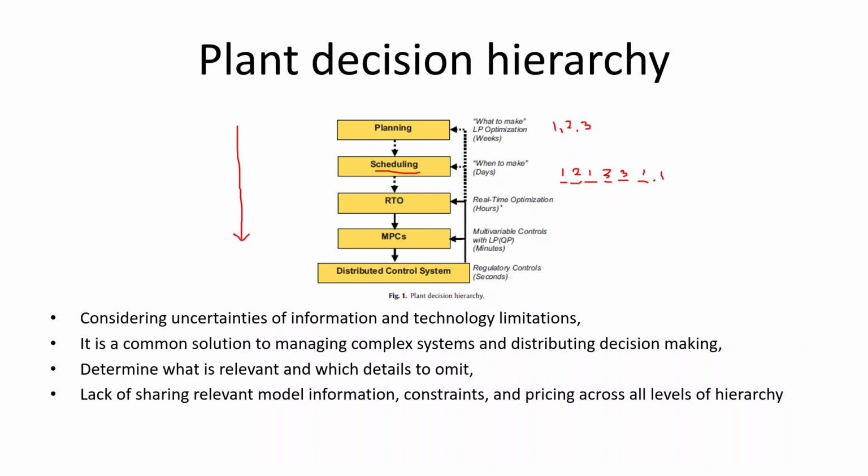So we have the plant data, and they make the model, and then from this RTO model, they will use it to say, right, what are the set points required for the plants, and then those numbers will be sent back to what they call an MPC, the model predictive control, as a set point. And then the MPC will also try to optimize for profitability, but from the control point perspective, and then that information will be sent to our DCS.